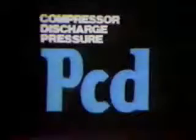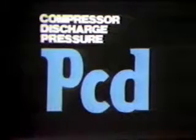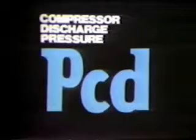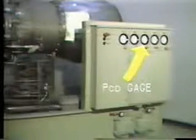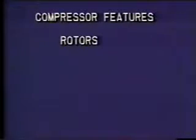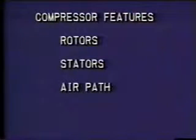This diffuser pathway is formed by the diffuser case, the compressor bearing support housing, and the turbine bearing support housing. At the rear of the diffuser, air pressure is the highest in the engine. Since this pressure is most important in monitoring engine performance, it's given a special name, the compressor discharge pressure, abbreviated in engineering terms, PCD. PCD is measured at the turbine bearing support housing and is an important display on the engine gauge panel.